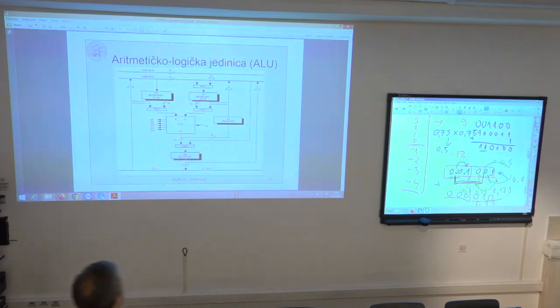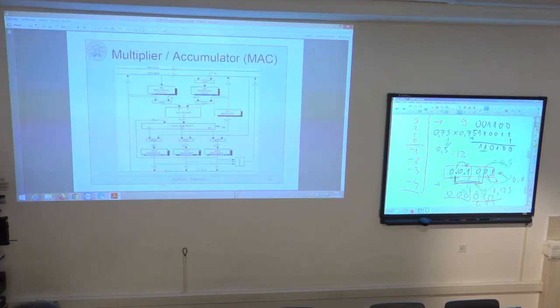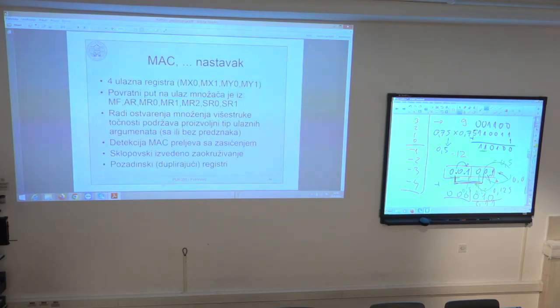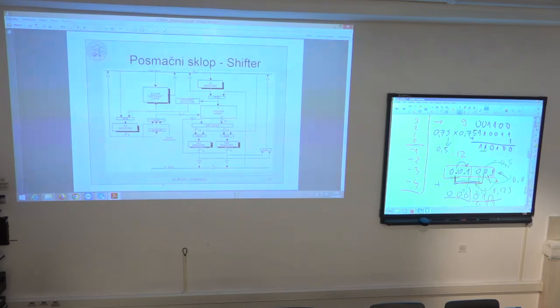Okay, then going further, we have 15 minutes more just to explain the shifter unit. It is the last unit that we have to describe of the three execution units. And this shifter is a special shifter. It supports so-called barrel shifting. With a conventional shifter, you only shift by one position, to the left or to the right. So you have shift left, shift right, or rotate left, rotate right, but only one position.